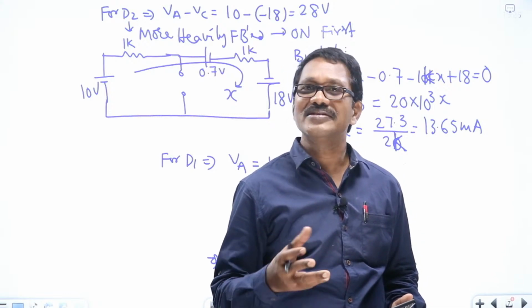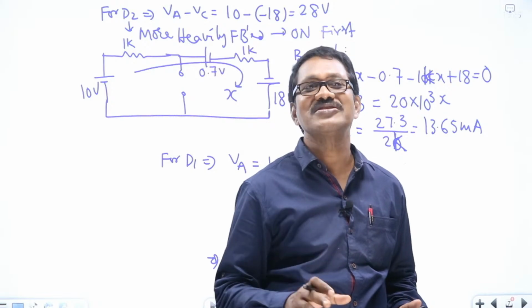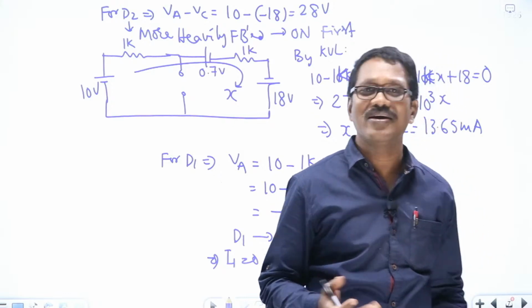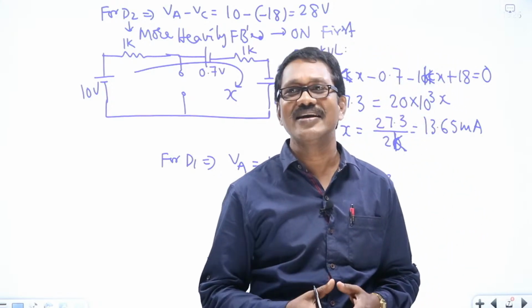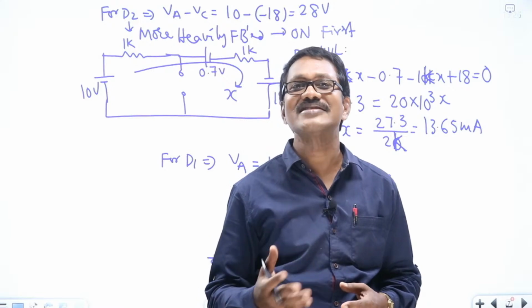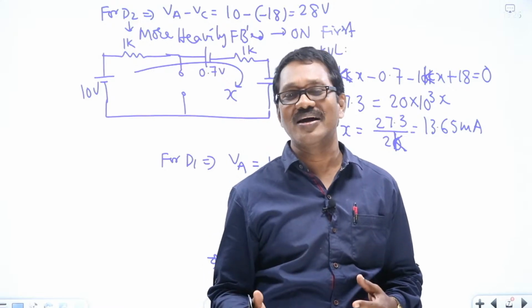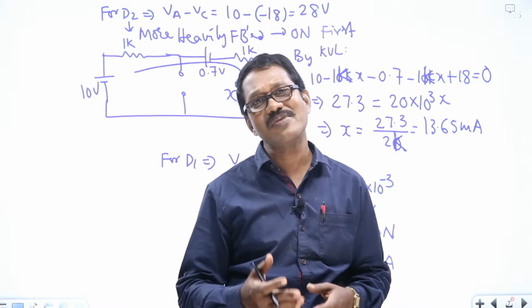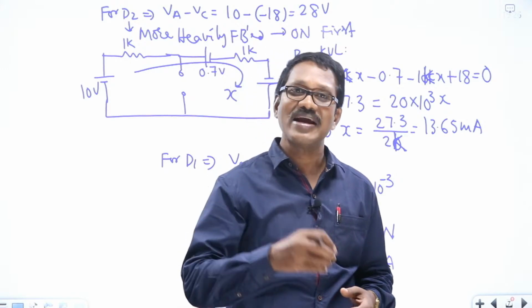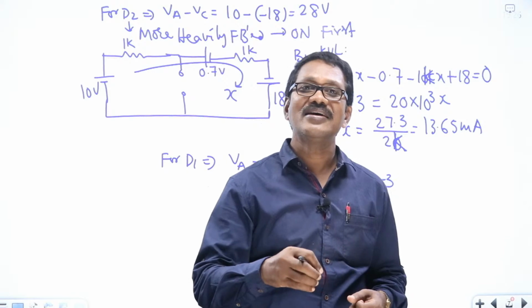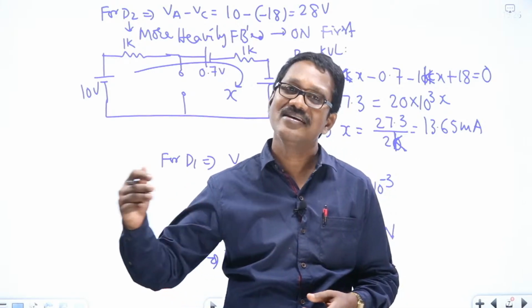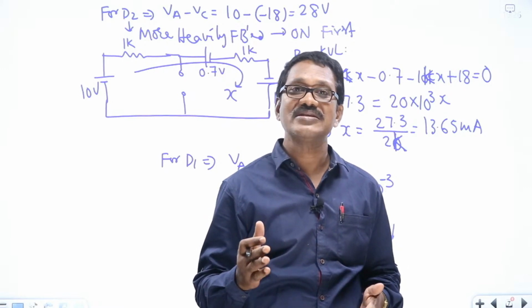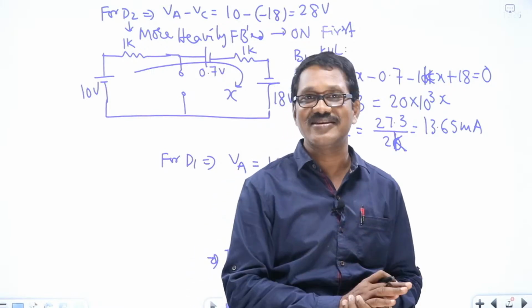Zener diode can also be used in the clipper circuit. What is the operation of Zener diode? When it is forward biased, it acts like a normal diode. On what basis can we say that the Zener diode under forward bias conditions acts as a normal diode? It is practically found that the V gamma for Zener diode under forward bias conditions is 0.7, which is same as an ordinary diode. Based on this, we can certify that under forward biased conditions, Zener diode acts as a normal diode.